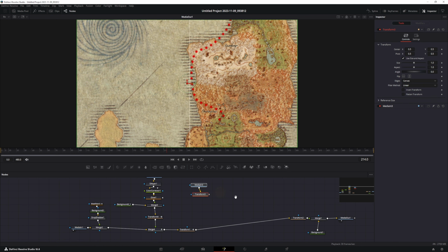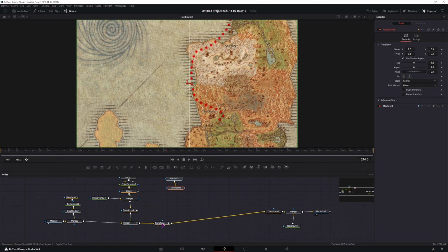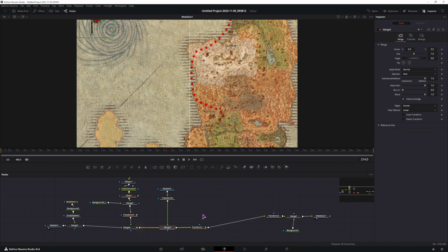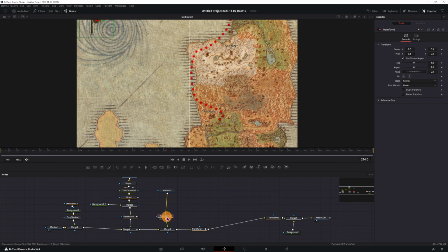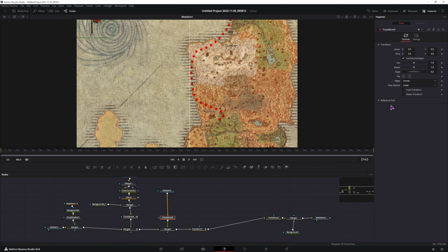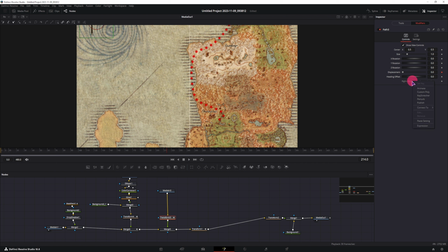We now have to do the ending image, which will be similar to this one. So this transform will go here. Let's just connect it so we can see it. So this transform has to be similar to this one. We'll have to connect the path to it. So click on the center position, path, modify, right click, connect it to the polyline stroke 1 polyline value. Go to the path tree, uncheck the displacement and set the displacement to 1.